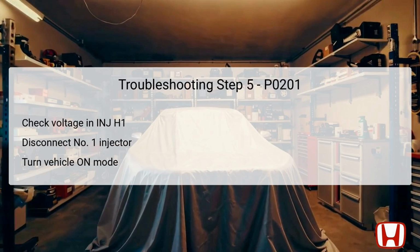For the fifth step in troubleshooting DTC P0201, the focus shifts to checking for a short in the INJH1 line specifically to power. You must first disconnect the number 1 injector via its 2P connector, allowing you to perform a precise examination. With the vehicle being switched to the on mode, measure the voltage between the PCM connector number 1 terminal number 17 and a reliable body ground.